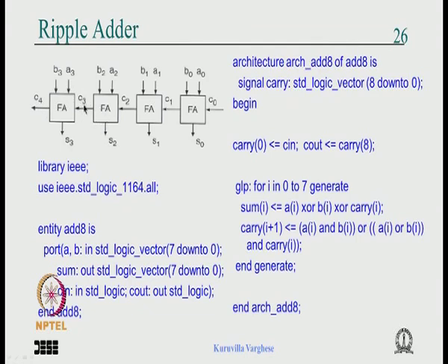By the time the carry input C3 comes here, there are 6 levels of logic and it delays everything. This sum is delayed because it is going to use C3. So when it comes to the 4th one, it is much worse. So that's a ripple adder.